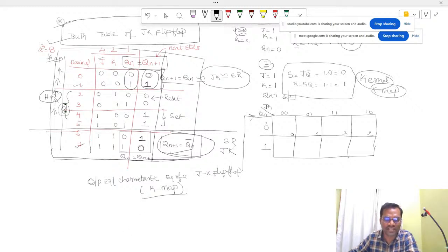Okay. So now we can see here. Now you tell me the combination. All zeros are there. You see these triple zeros. What is the output? Everyone see here. So the output of this, we are going to get the equation, which is Qn plus 1. So three zeros are there, row-wise zero, column-wise zero also. All zeros are there. What is the output? 0. Now 001. What is the output? 1. Next 011.